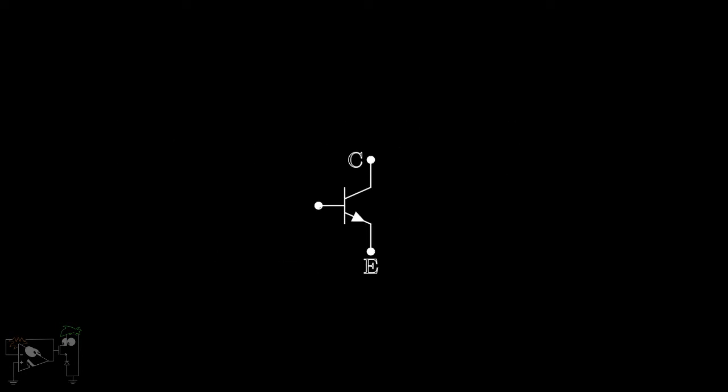In this video, we'll take a look at log amplifiers, an amplifier which outputs the natural logarithm of the input signal. We'll also see how to change this into an antilog amplifier. You might have guessed that we need a device which has a logarithmic or exponential IV characteristic. Can you think of which device follows a logarithmic relationship? It's none other than a bipolar junction transistor, or BJT for short.